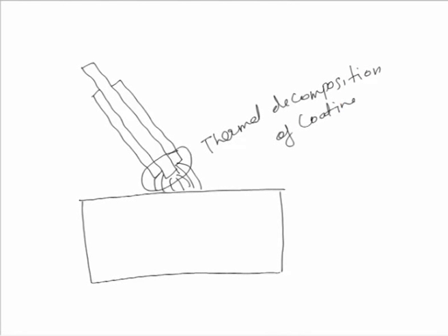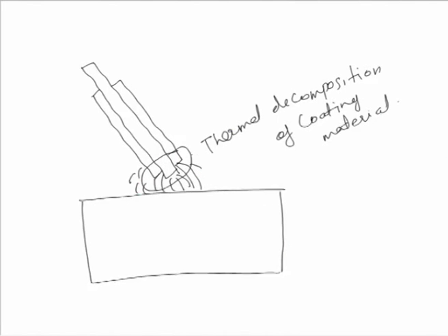of the coating material. So, by the heat of the arc, when the coating material is decomposed, a lot of inactive gases like carbon dioxide and carbon monoxide are produced and form a cover around the arc and the weld pool to protect it from the atmospheric gases.